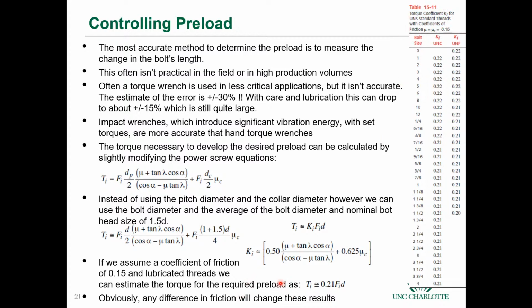The reality is that we don't know friction. We can't measure it beforehand. It's just there. But these are not unreasonable values to start with, especially if you have room in your design to slightly oversize the bolt and get to where you have a pretty good level of confidence that you are going to be applying close to the preload that you want.